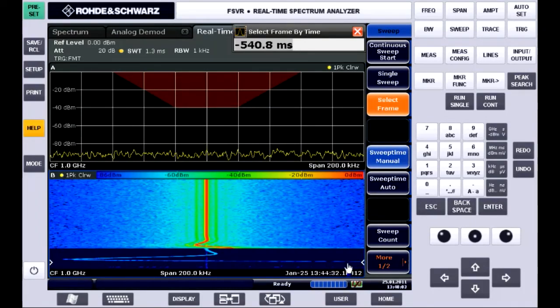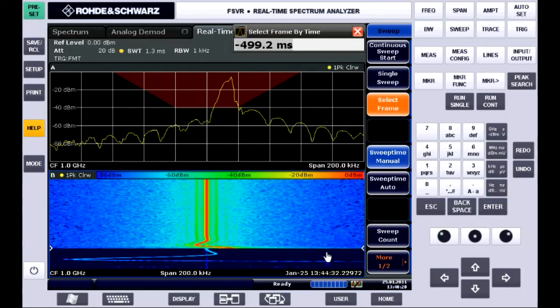So now I'm eventually going to see this signal swinging in from the high side. There it is. It swings low. There it's about 90 kilohertz low. Swings back, overshoots on the high side, settles down, and then we'll see the power jump up when the power amp kicks on. That's what defined my trigger point. That's when the signal entered this red area that the mask we defined.